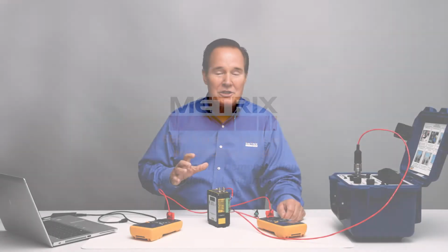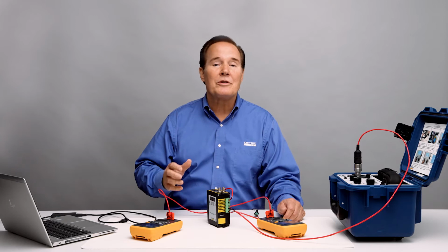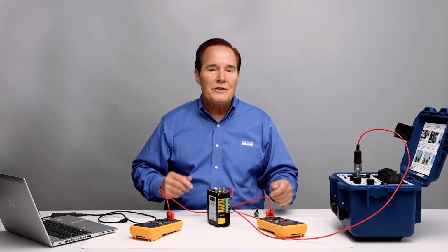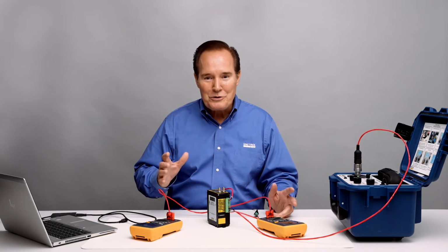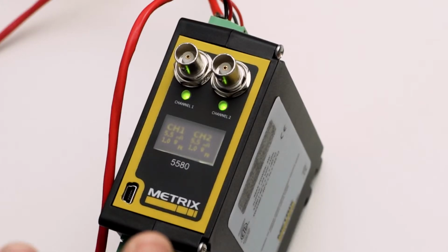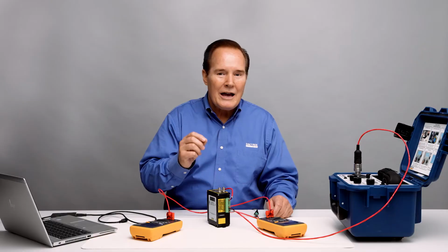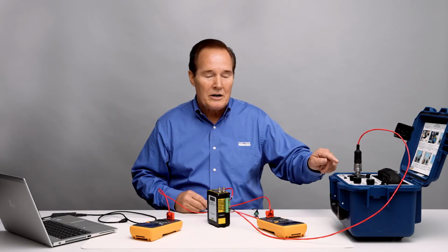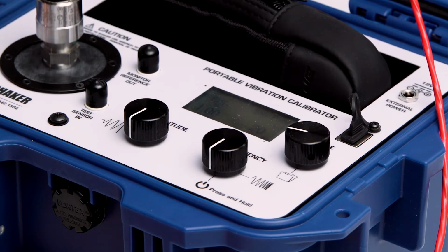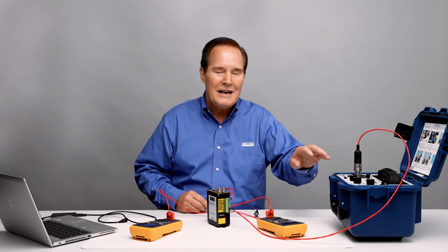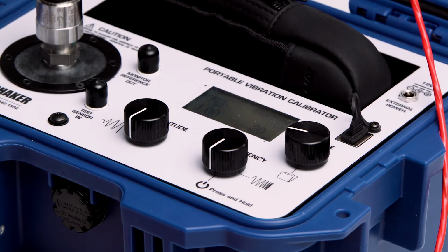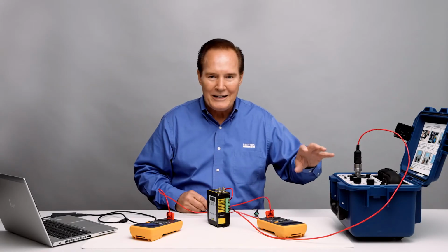Now, this same demonstration I'm doing with the 5580, I can do with the SW5580 switch. But today we're going to use the 5580 just to show you that works too. So on the 5580, in channel 1, I have an SA6200A accelerometer, and that's what you see here. I have this HI903 shaker, this Hardy shaker, set at 1G at 20 Hertz. This is simulating a reciprocating compressor out in the field. So that's what I'm simulating, and it's running.